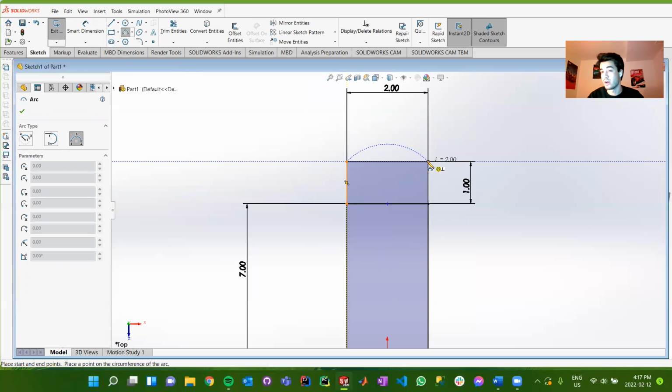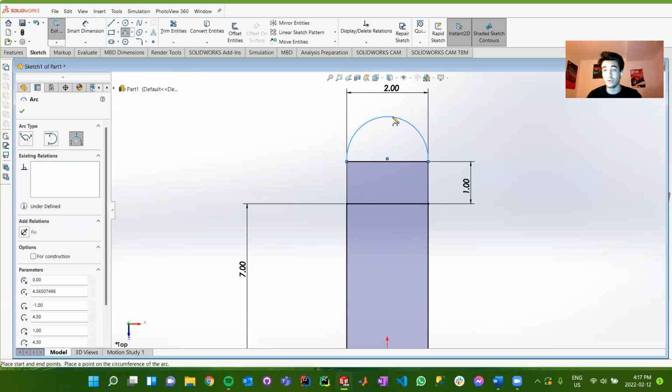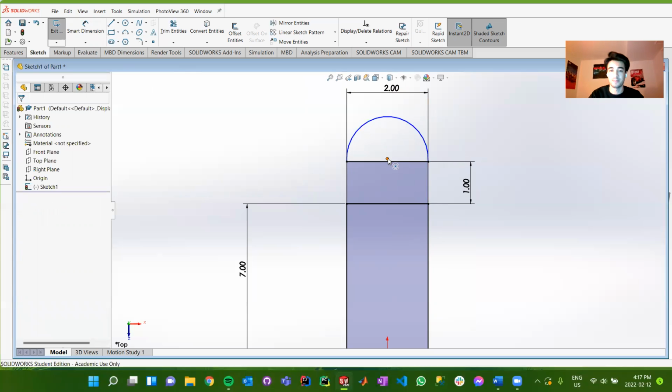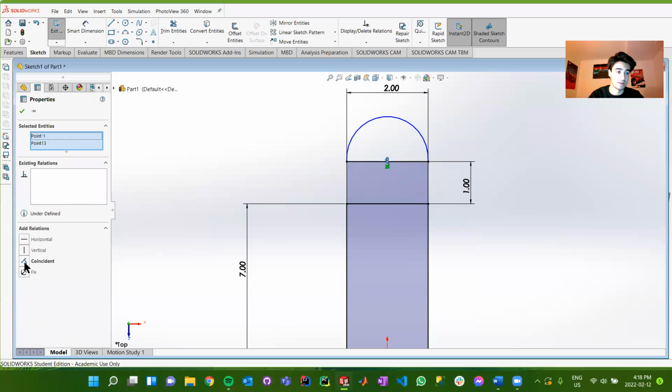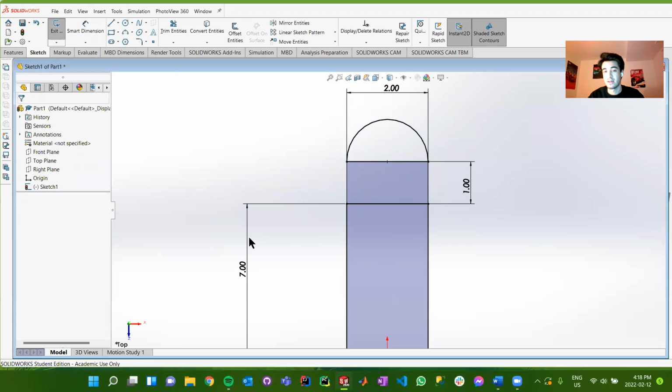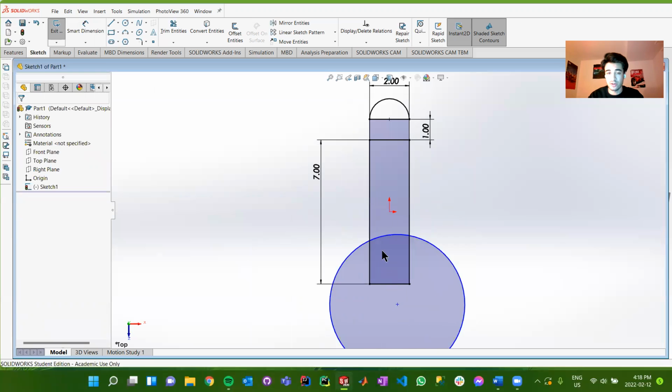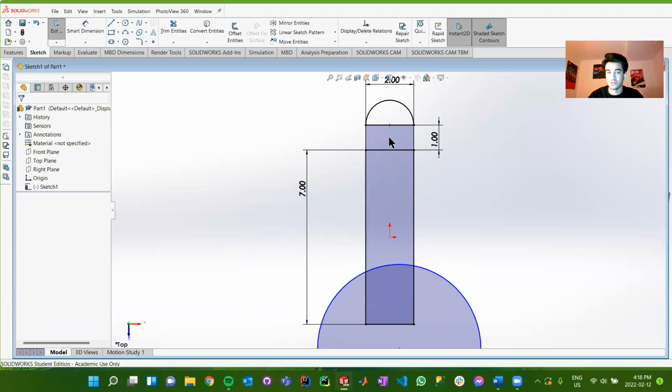Now relative to what our original specifications were, we'll have a lot more space to put the hole for our chassis compared to what we had before. So I'm going to constrain the origin of this arc, or sorry, the arc center, to the midpoint of this particular shape here. So we can press coincident. There we go. Now you'll notice that in terms of our contours, we have these shaded in contours over here, but up here, it's not shaded anymore.